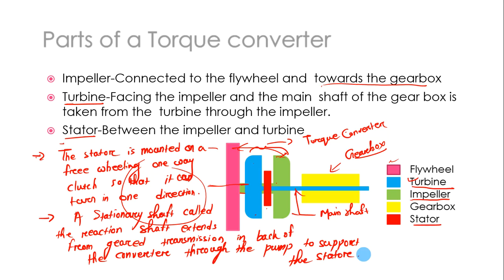So here, this setup of the turbine and the impeller stays inside a box, inside which the oil is completely packed. So basically, as I just said, it is splined to the input shaft, which rotates inside the reaction shaft and connects the curved blades to project most of the oil into the hollow cylinder parallel to the axis of rotation.